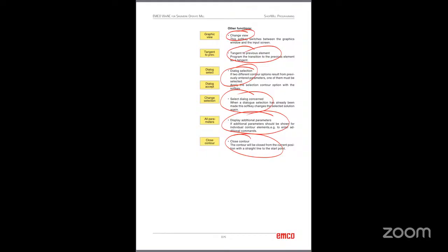For example, you have a rectangle. You need to change the corner to rounded. So line, circle, R20, line. Using the circle element with a 20 mm radius, you will get a rounded corner.